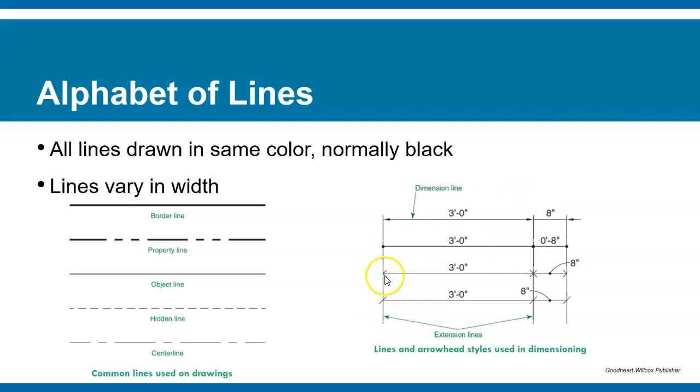This is an arrow that's not as sharp, but it's still an arrow nonetheless, representing the point. And then you see a slash. Just consider it half an arrow, if you would. And you can see that it slashes through the point at an angle, and like here, you see multiple slashes. So these are the different ways you would see dimension lines.